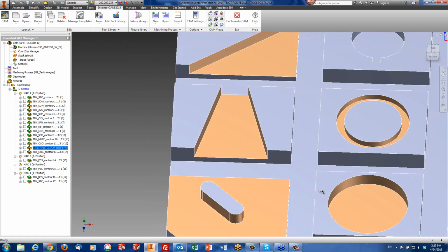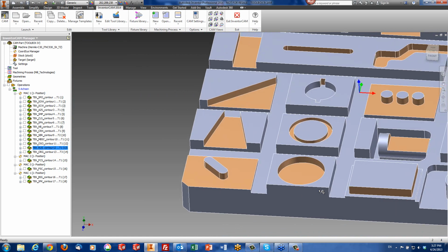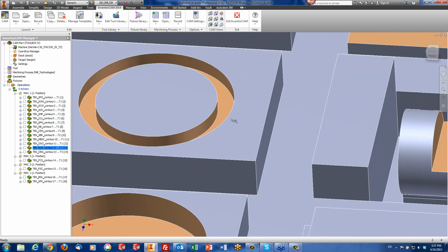Now these are in the program itself. Anyone can go ahead and start using it. I just want to let you know that we have these options. Now one more option I would like to show you is this one over here called O-ring. This is a typical operation that happens in many machine shops, where you have to put an O-ring on the inside of the part itself for whatever reason. And the way you would love to work on it is to first go down dead center, maybe even spiral around the dead center, and then clear off the walls.